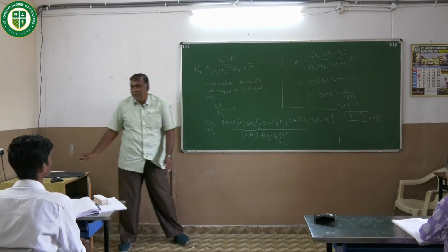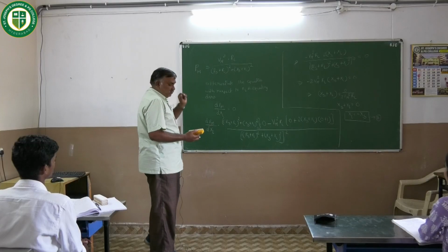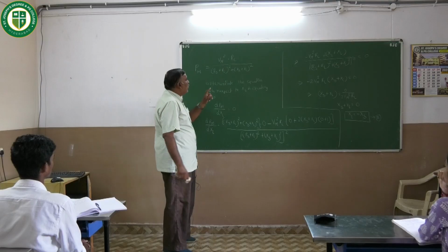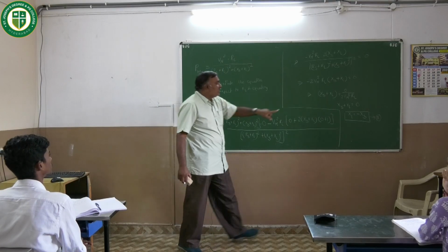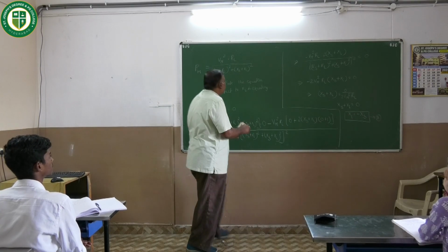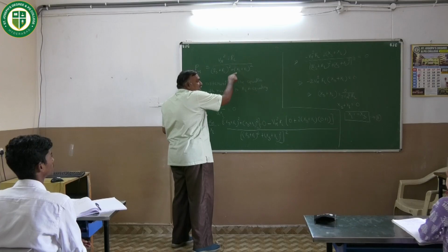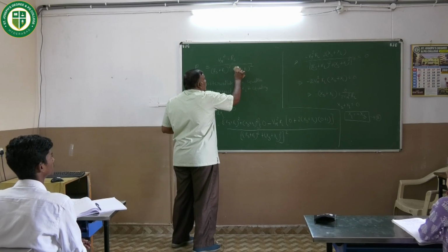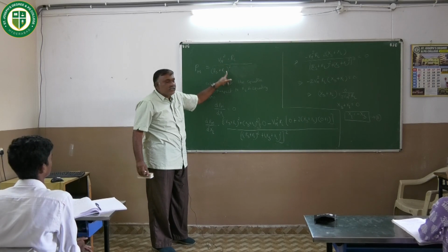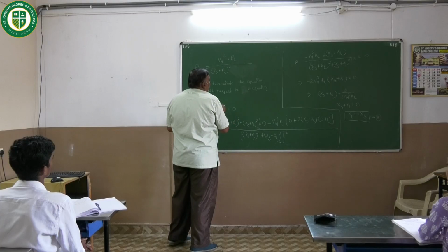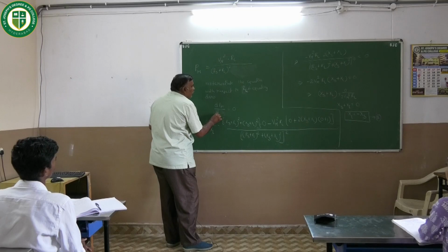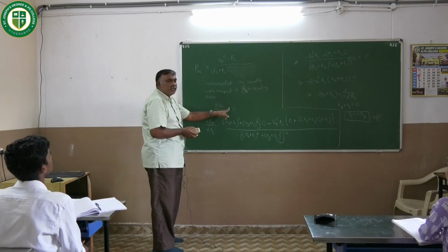Fine? Right. Now we will differentiate the same equation with respect to RL after substituting this first condition. If I substitute XL is equal to minus XS, then minus XS plus XS will cancel with each other. So the term that is left is Vm square into RL by (Rs plus RL) whole square. Now you need to differentiate this with respect to RL and equate the term to 0.